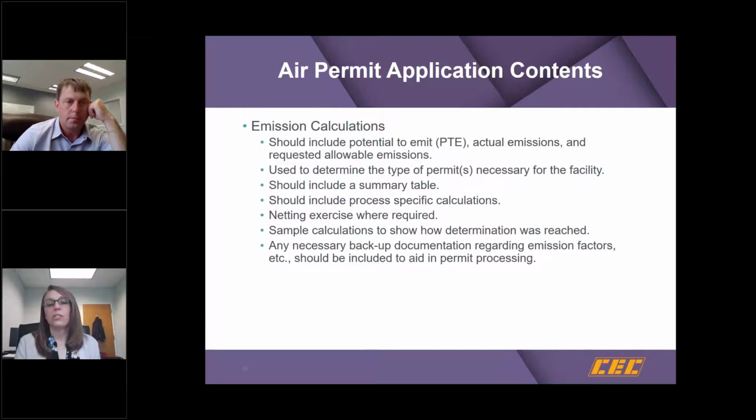All of the calculations should include a summary table and then process specific calculations. So you want to do it per emissions unit as well. You want to look at the source as a whole, look at all of the VOCs that a facility emits or all of the particulate, and then break it down by source too. And sometimes netting is required, but that's for really large sources. And again, that's a complicated process that usually we only worry about with PSD and NNSR.